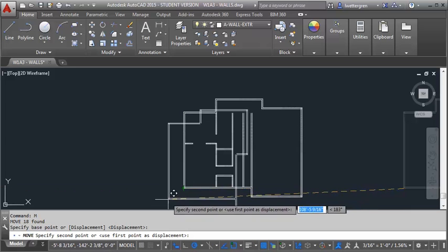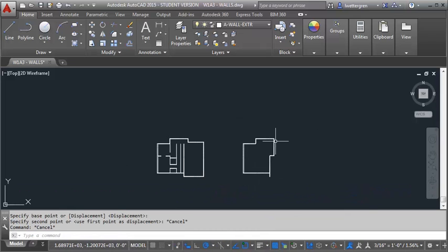with where it should. So that's a good way to double check that your dimensions are correct, because if your exterior walls are not correct, then it's kind of a snowball effect. The interior walls won't be correct, and it just keeps getting more and more difficult. So you want to be really, really sure that these exterior perimeter walls are the correct length and that they're drawn accurately. So like I said, just keep using that line command, offset, trim, fillet, extend, all of those, and try some different things. It's important to kind of experiment and see what the different things do, but hopefully this will help kind of get you started with getting these plans drawn.